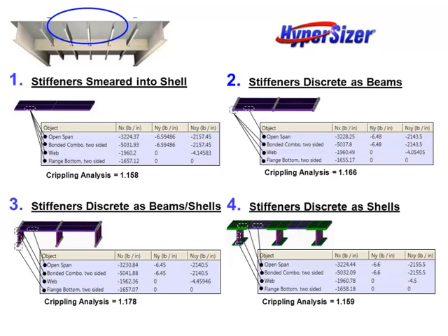Compared here are the individual panel object loads, extracted from the discrete FEM mesh. All four methods give accurate results for axial and longitudinal bending moments. When in-plane shear forces are also applied, techniques 1 and 4 prove to be the most accurate, but all are still accurate enough. Regardless of which modeling technique is used, Hypersizer extracts loads from the FEA solution consistently and accurately.